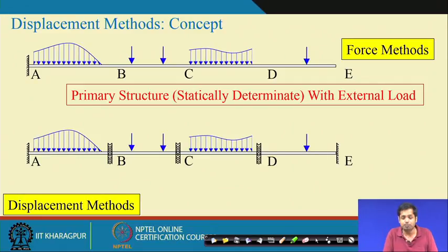For instance, here the displacements were theta B, theta C, theta D and theta E. If we remove them, it means we do not allow this structure to rotate at B, C, D, E; the rotations at B, C, D, E are 0. How can we make that? By assuming there is a fixed end at joints B, C, D, E, which prevents rotation from occurring. Okay. Now,